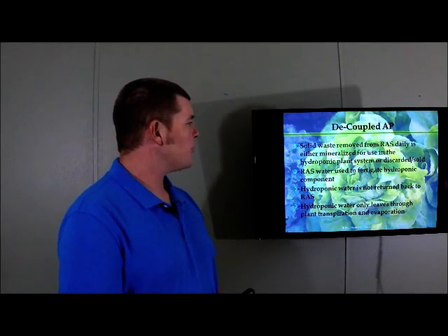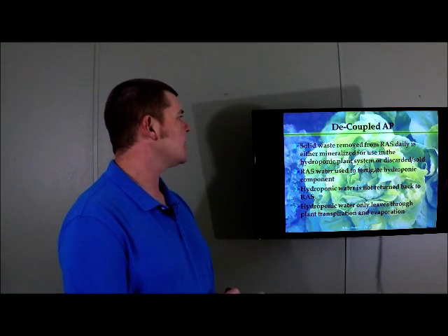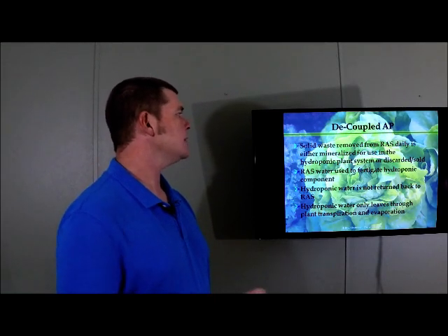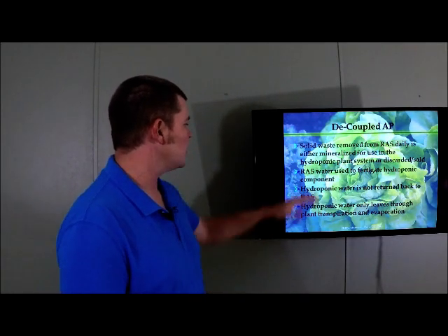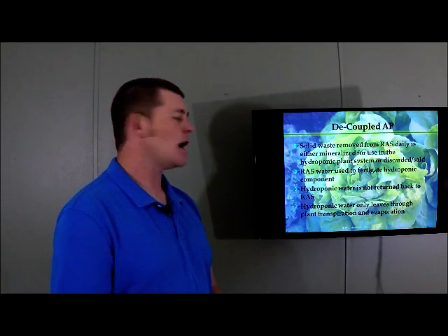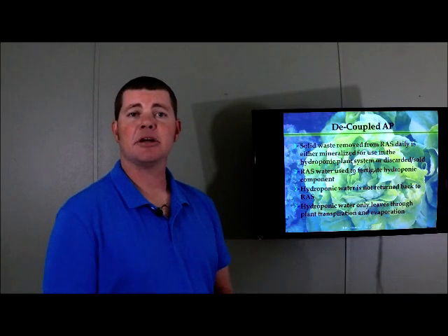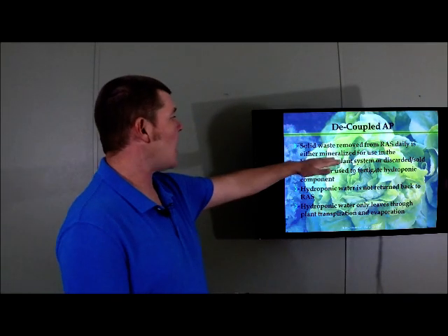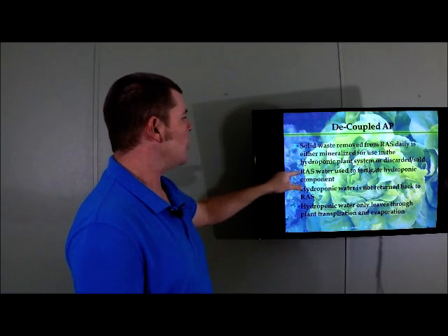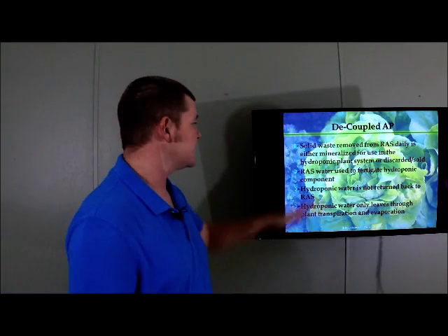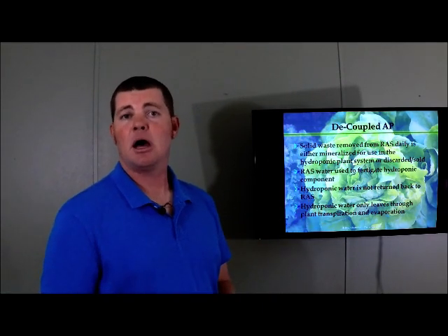Solid waste removed from the recirculating aquaculture system daily is either mineralized for use in the hydroponic plant system or discarded and sold. RAS water is used to fertigate the hydroponic component. So we use the water from the recirculating aquaculture system to top off and supply nutrients to the hydroponic component. Now, if we're not using a mineralization tank, and we're just discarding our solids, then all of the water for the hydroponic side is coming directly from the RAS system, and we're topping the RAS off with fresh, clean water.